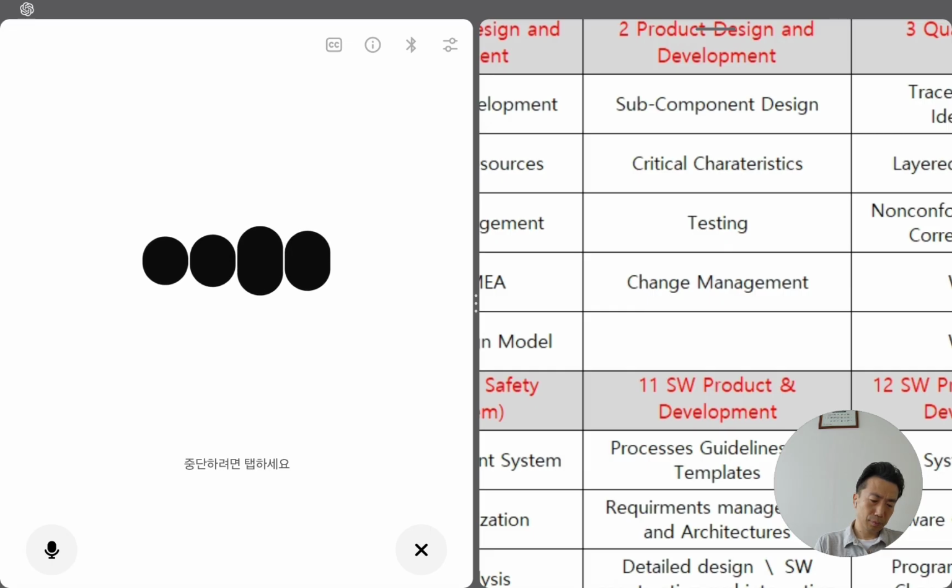Here is the correct way to say it in audit English. In the drawing, critical characteristics are marked with a triangle symbol. In the DFMEA and PFMEA, they are flagged with CC/SC notation. In the control plan, critical characteristics are flagged and linked to special inspection methods. So David, instead of saying CC/SC, it's clear to say triangle symbol, diamond symbol for drawings, flagged with CC/SC notation for FMEAs and control plans. Would you like me to make a short practice script, auditor question plus supplier answer, using these words so you can practice saying triangle symbol, diamond symbol, flagged with CC notation naturally?